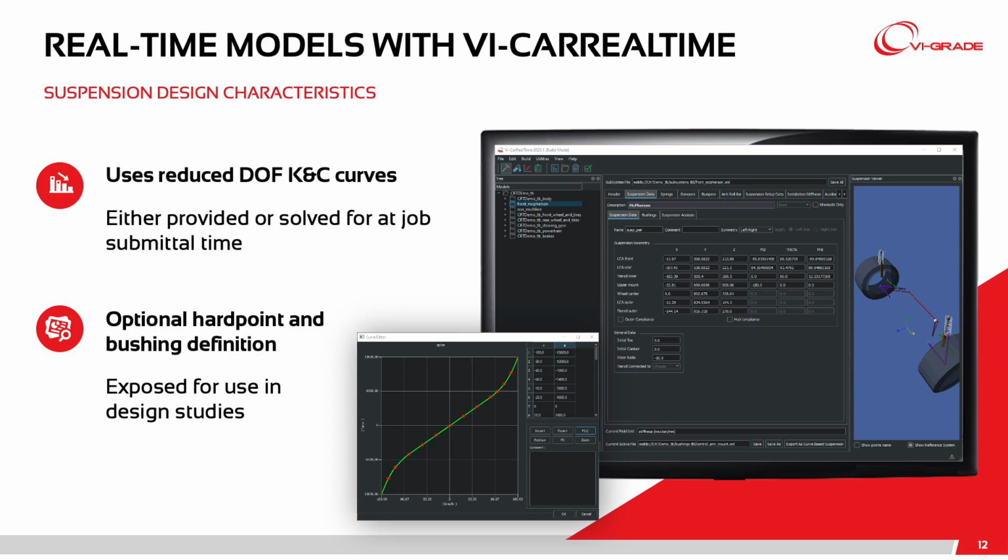So when it comes to suspension design, I mentioned that we can use KNC curves. And in fact, that's a big part of how real-time modeling is done so fast, is that the degrees of freedom in the suspension are reduced down usually to 2 per corner. It's the jounce or vertical response, and then it's the rotation of the wheel itself. And then all the other degrees of freedom get defined as KNC type curve lookups. But that obfuscates a little bit the suspension design. That's great from a solver standpoint.